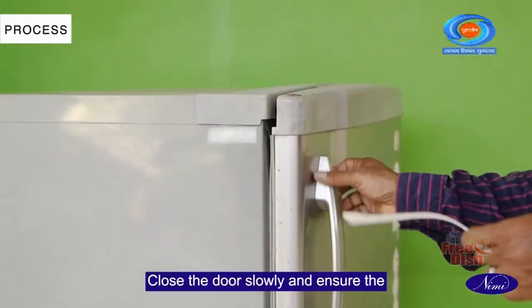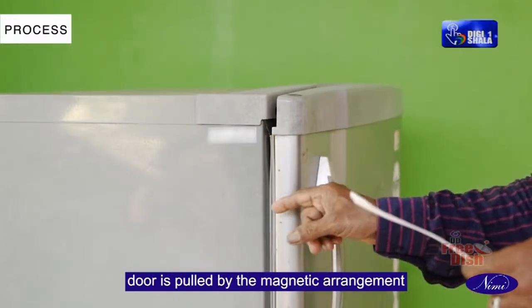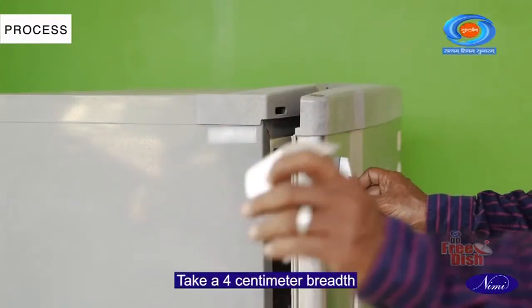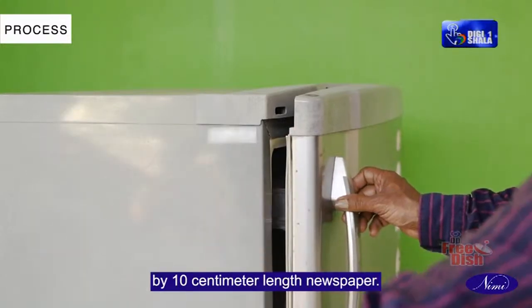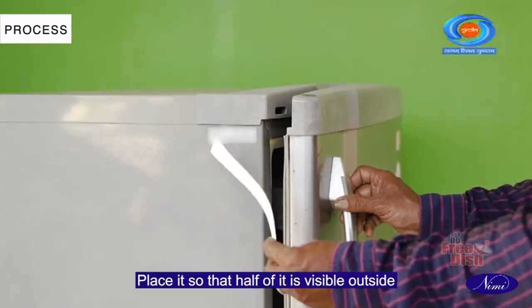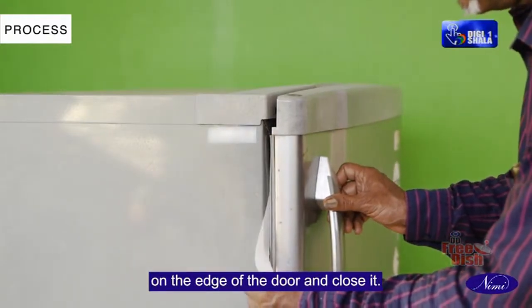Close the door slowly and ensure the door is pulled by the magnetic arrangement when it reaches the nearest closing point. Take a 4 cm breadth by 10 cm length newspaper, place it so that half of it is visible outside on the edge of the door and close it.